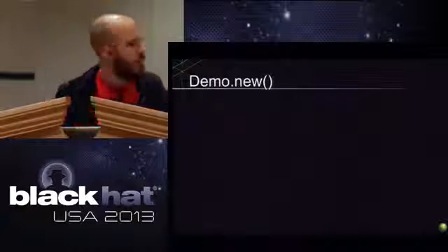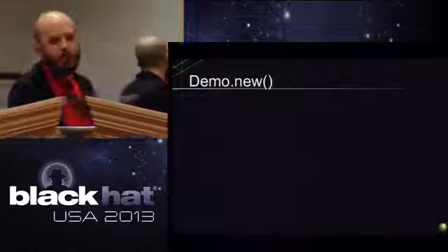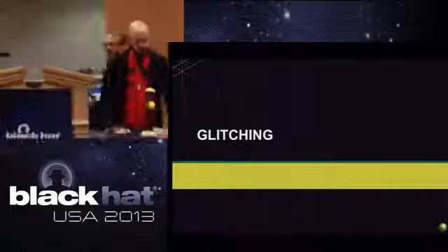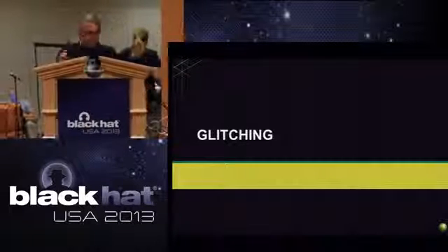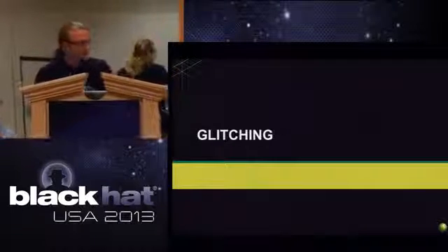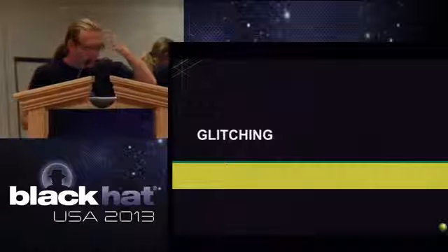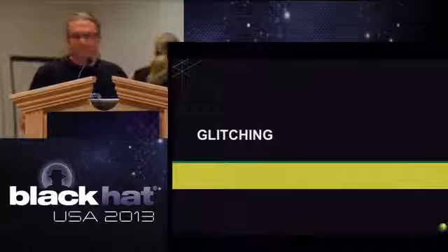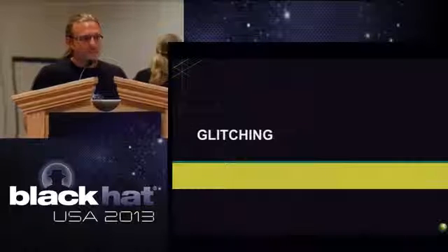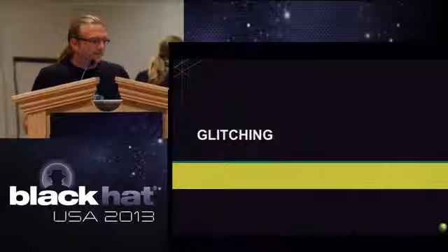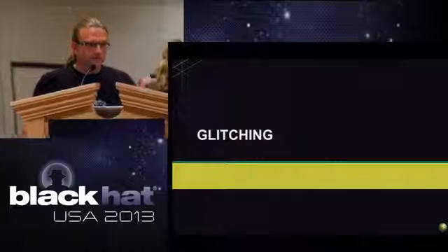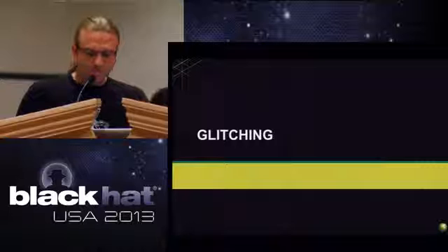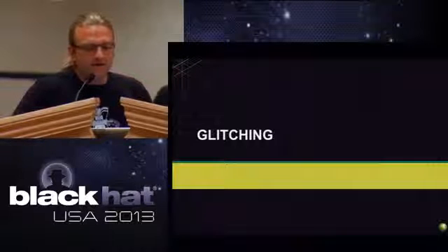All right, so that's kind of the bulk of it. I think we've got a couple minutes that we'll cover glitching real quick. If you remember way back, we talked about there's some bits that can be set that don't let ICE be enabled anymore, so you can't actually do any live debugging on the board, unless you magically hit it within that first 30 to 60 cycles. Once you do, you can get away from that.